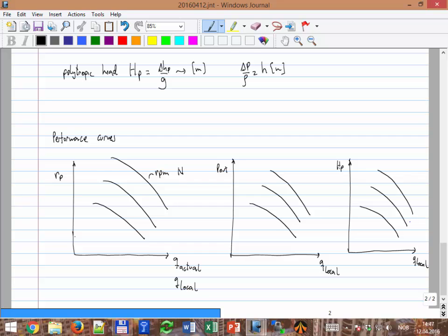Okay, the thing is, something that is very different to pumps is that each one of these plots is a function. It depends on the conditions of pressure at the inlet, temperature at the inlet, molecular weight of the gas, and K. The same machine, exactly the same machine, if now I change the inlet conditions, it might look something like this.